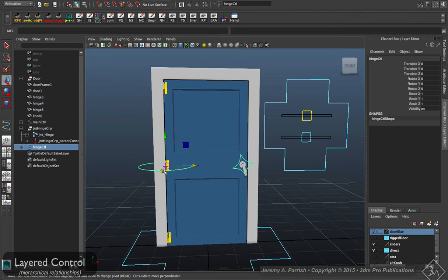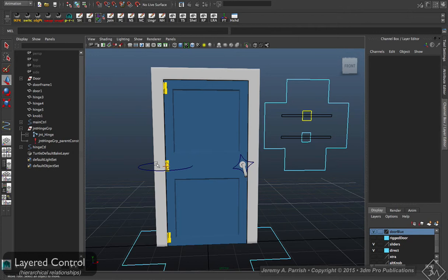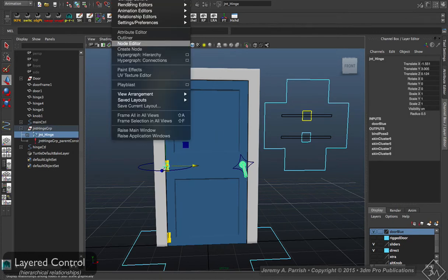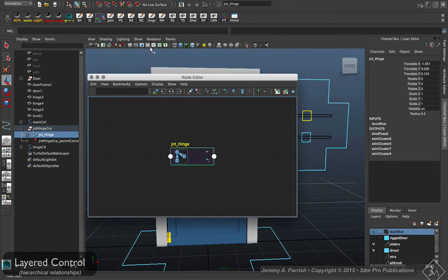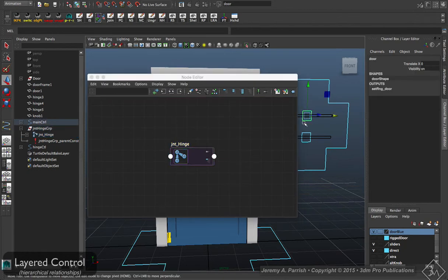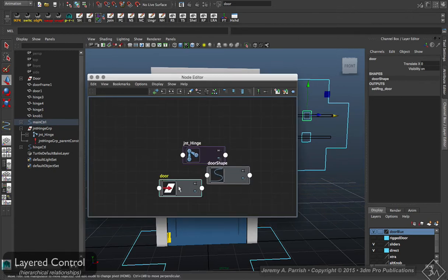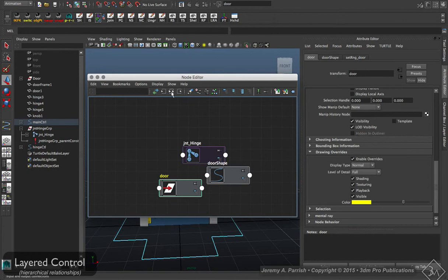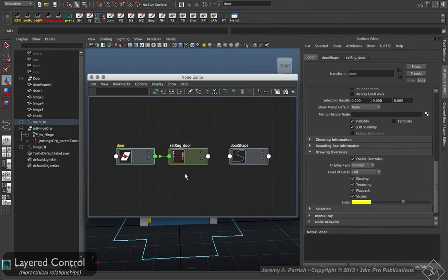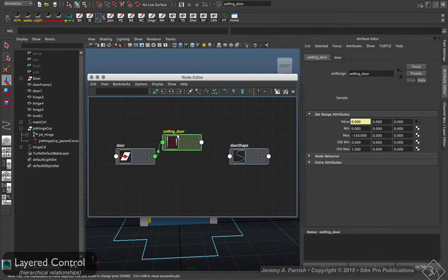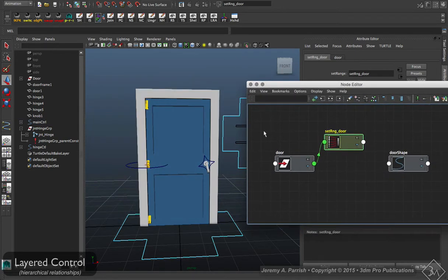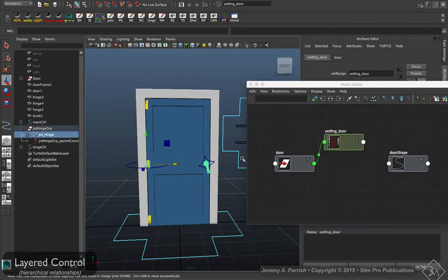So all I have to do is make that final connection. So I need the joint itself. I need to load up the panel, node editor, and I'll need the set range node. So what I can do is select the curve that's already connecting to it, load that in here, and select it, and then use this button here to show all the incoming connections to it, so I can get the range node, but I'll have to reload the joint.